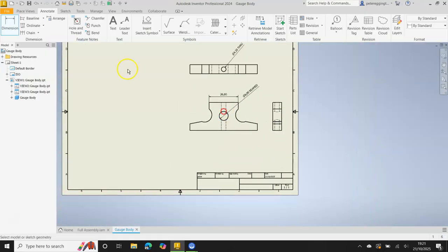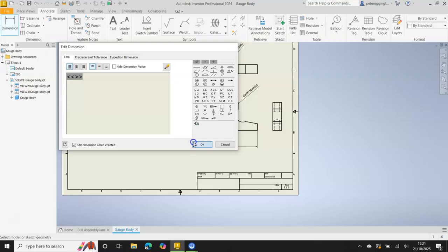We can now go around looking at the drawing that you've got in front of you and try to place on all of those dimensions. Again, there's no right and wrong answer here for how you do them. I'm just going to stick with the dashed lines to begin with. I probably am going to change those as we go a little bit further. Sometimes rather than click on a line you could click on 2 green dots, a little bit like that. And sometimes that's really useful when you're trying to go to the center point of something, because it'll bring the measurement out correctly.